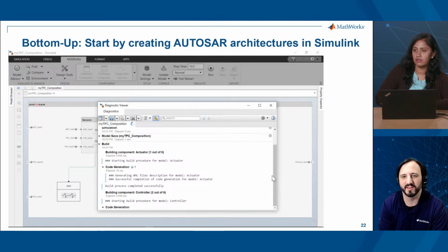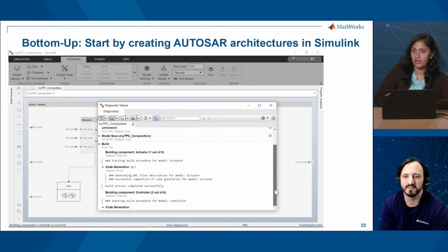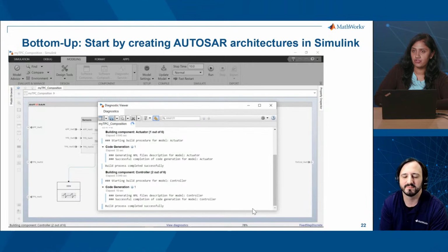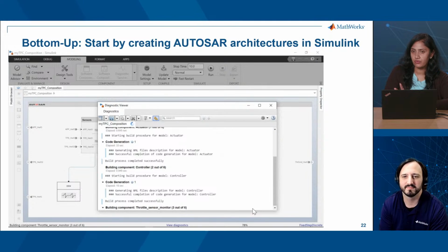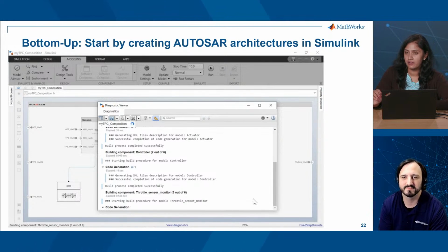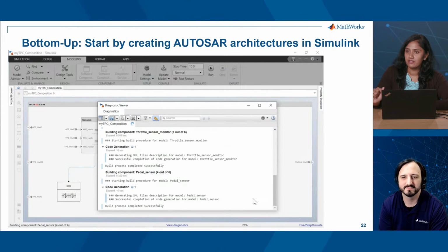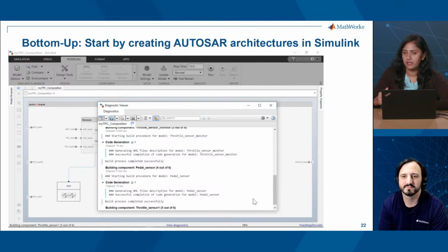And so what you were saying earlier was that this ARXML includes the structure or the architecture of the model, but not those Simulink behaviors, right? So those will still be separate from my ARXML? That's right. I will generate the code in a separate folder and the ARXML in a separate folder. ARXML is merely an architecture piece. Whatever logic was implemented in Simulink will all be in the C code.